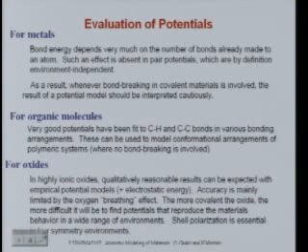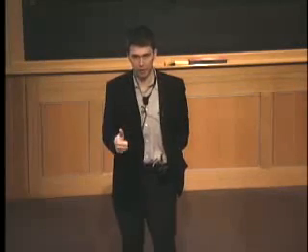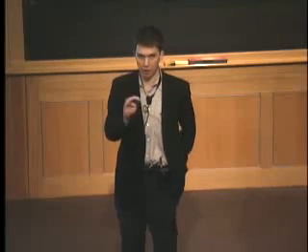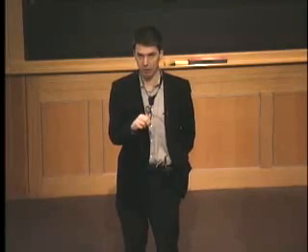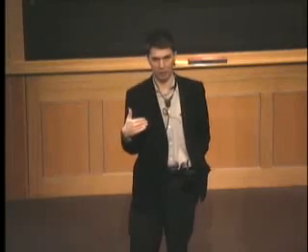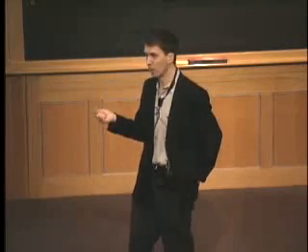What I think we've seen is, in metals, you have the issue of coordination. You should remember that bond strength depends on coordination. And you should remember how that showed up in things like vacancy formation energies, and in things like surface contraction. When you make a surface, the layers tend to contract in. So if you have fewer bonds, they're stronger. And that's the problem for pair potentials.